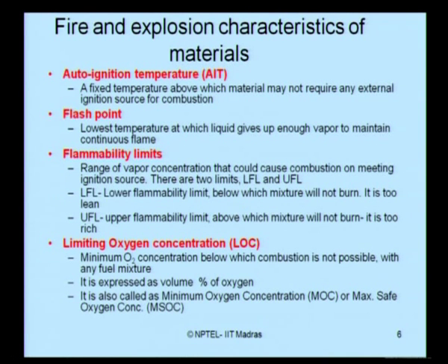So, the limiting term, as you have understood correctly, quantifies the minimum oxygen concentration below which combustion is not possible. Let the fuel mixture be of any kind, if the oxygen concentration present in the scenario is lower than a minimum value, then combustion will not be possible. Generally, LOC is expressed as volume percentage of oxygen. Some literature refers to this value as minimum oxygen concentration, MOC, or maximum safe oxygen concentration, MSOC. Both of them refer to virtually the same meaning as limiting oxygen concentration.